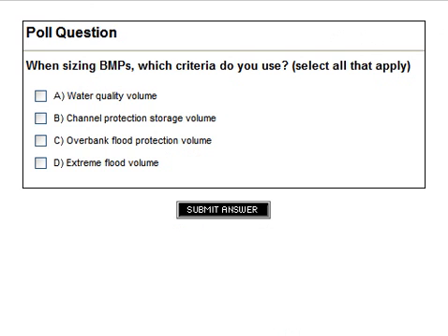What we mean by that is something like the 90% storm event that was mentioned a couple of times, and we'll explain in a little more detail, or perhaps addressing the one-year 24-hour storm might be another example. These can vary from place to place, but what you're trying to do is address water quality issues through these criteria. The second one is channel protection. Here again, it might be something like the detention of the 24-hour one-year storm. So you might have some criteria in place like that.